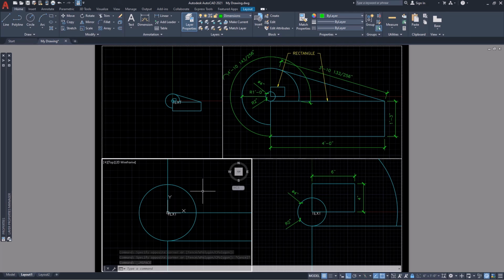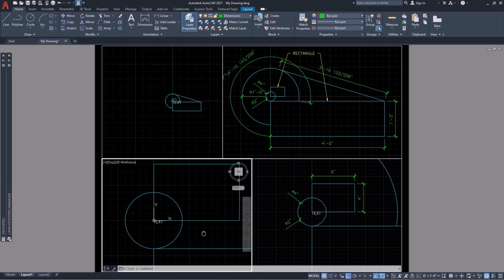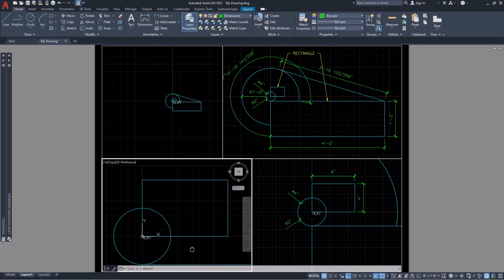Unlock the viewport window. Pan the small circle and small rectangle in the view so that they are generally centered in the viewport window, and then lock the viewport without exiting the viewport window back to paper space.